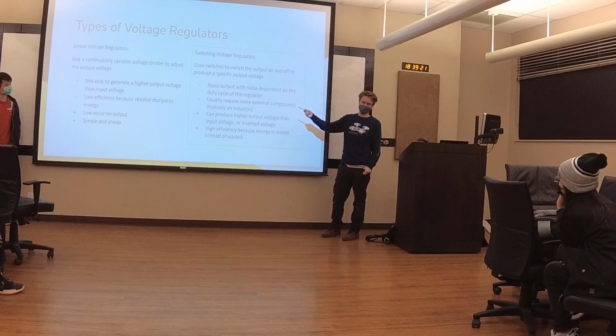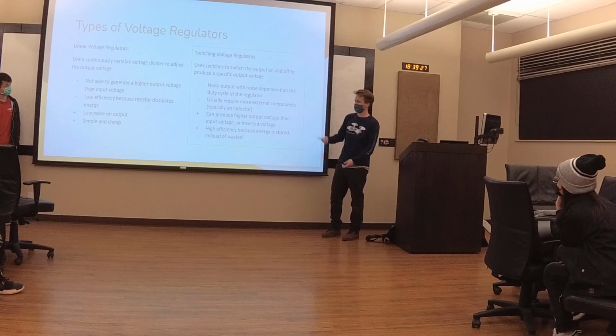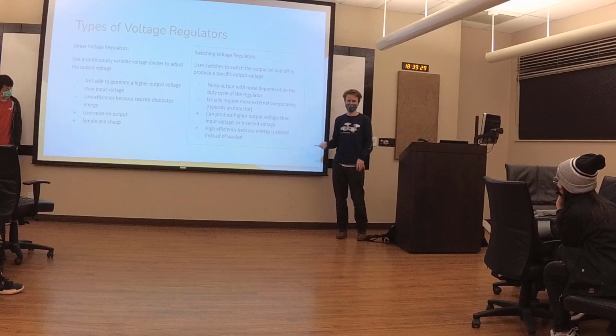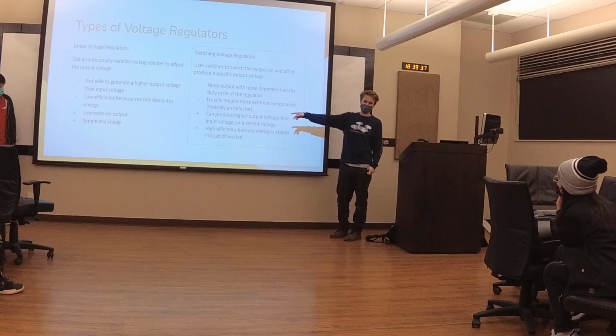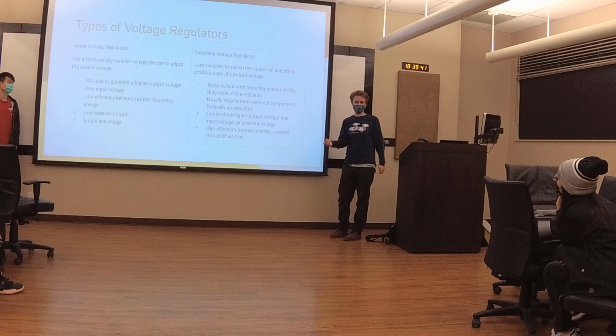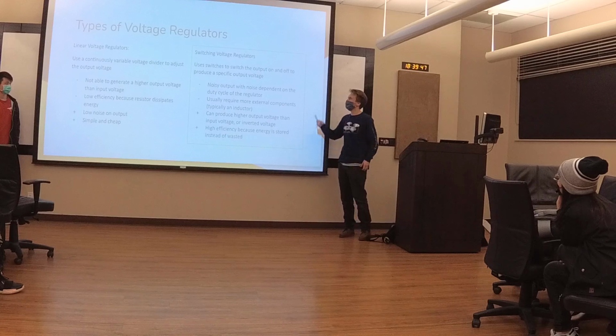The reason we're not going to be using them is because they can't raise a voltage, they can only drop it. The other problem is that they are not really efficient because a resistor dissipates heat. That heat is energy that you could have used for something else. That being said, they're really nice because they're really simple, really cheap, and they have low noise on the output. The reason they have low noise is because there's no switching inside them. It's just dropping voltage across the resistor.